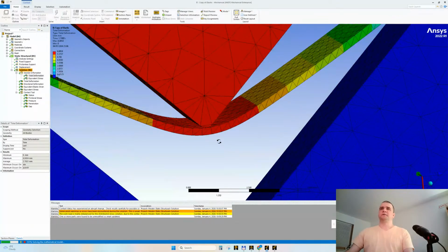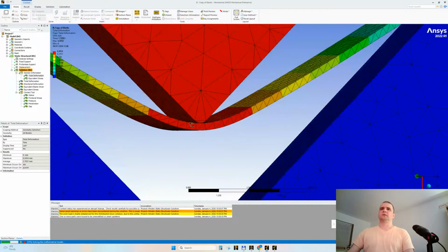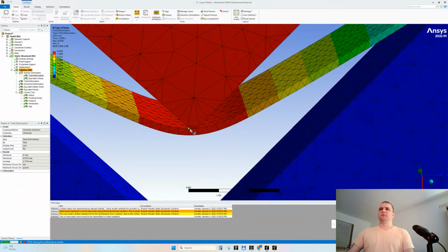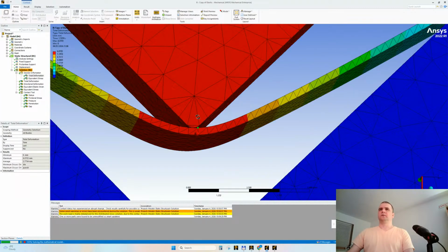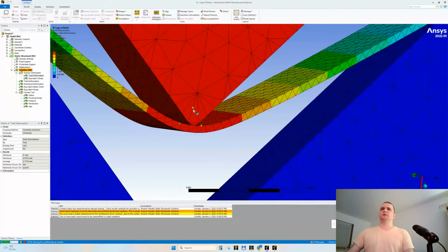Also, there is this reason, the fact that the nodes should encounter other nodes. Yes, so these nodes, let me change the cursor to node. These nodes from here or from here, from other side, should find nodes here on the punch. And if you have only one node here and one node here, you don't have other nodes except the mid-side nodes.